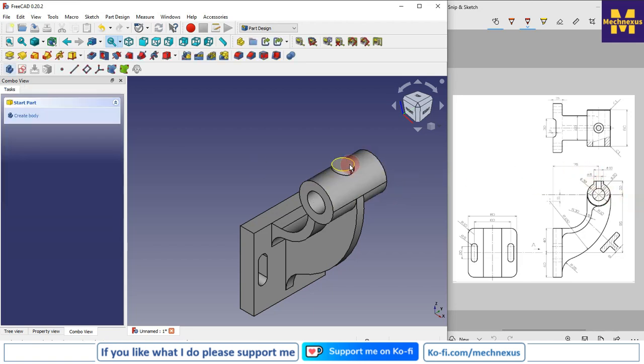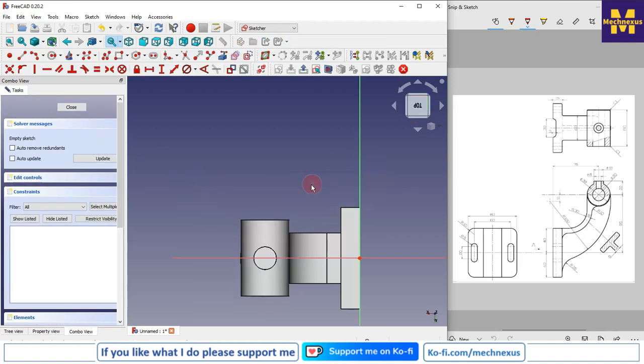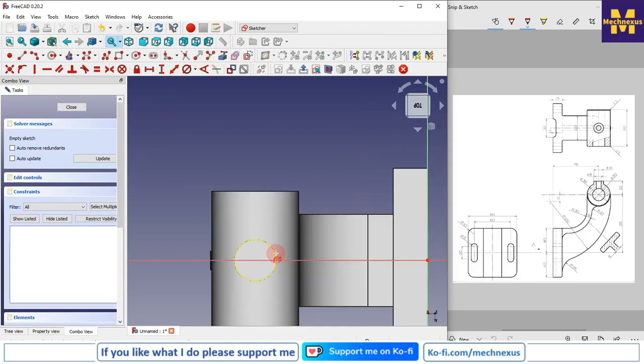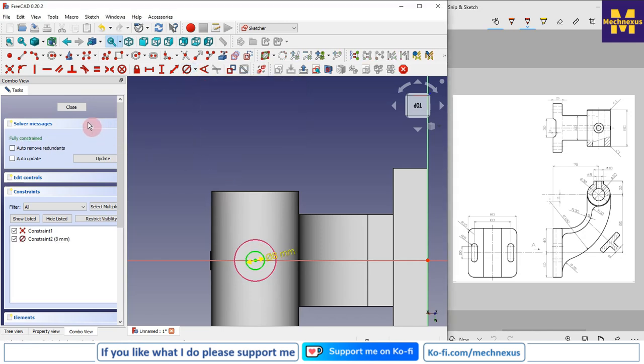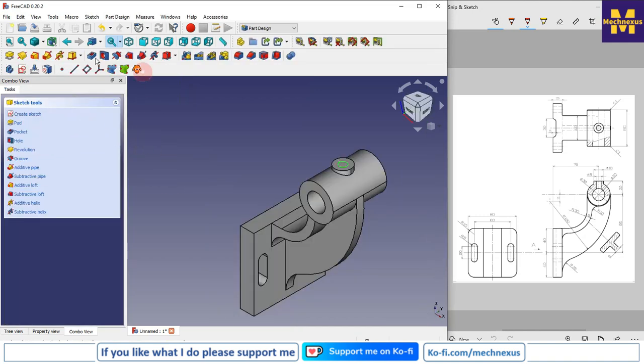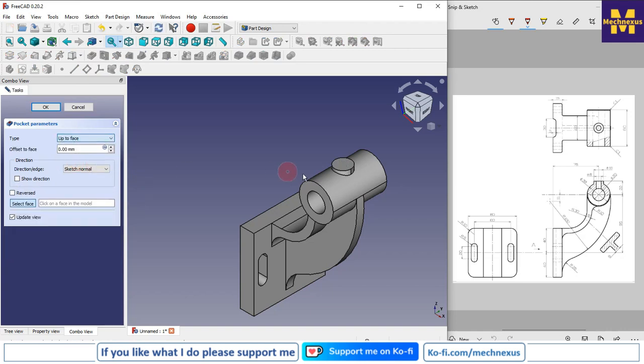Now from this top boss there is also a hole of diameter 8, so select this face, create sketch, and project the circumference, create a circle of 8 mm, diameter 8, close, extrude cut, and from here select up to face, say OK.